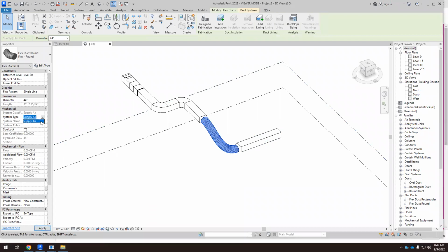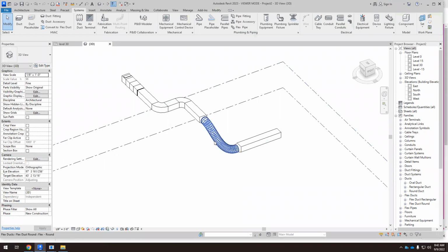If we make a mistake and we insert a return air duct, then it won't work, because now we have to calculate things. So first we have to design the layout, and then we have to calculate the airflows, and then we have to calculate the size of the ducts, the speed of the airspeed in the duct. So it's not just a question of designing the layout and okay, so I have connected the air handling unit to a diffuser. That's it.